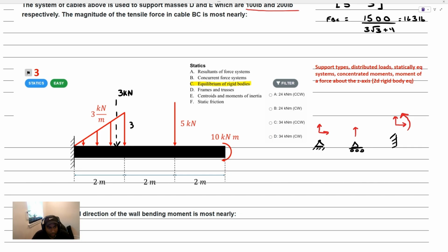This is a triangle here. So I always remember the 1/3, but some people get confused on whether it's a third of the way from the big side or the small side, right? And how I always remember it is at the centroid, you know that left and right of the centroid point, their moments must balance, and that's why this is considered the centroid, right? This large area is producing a moment about the centroid.